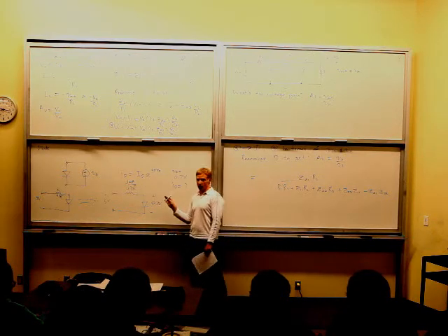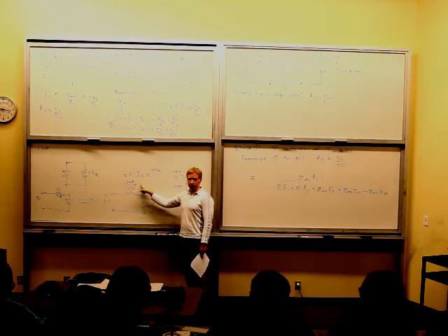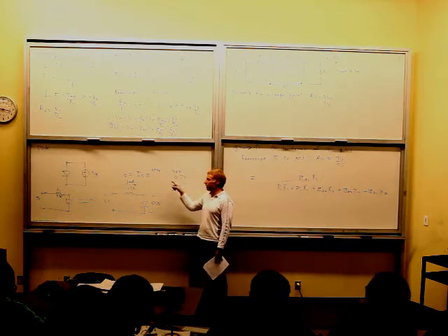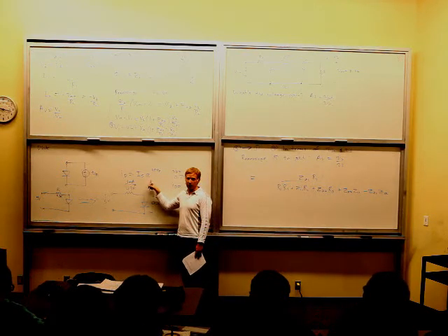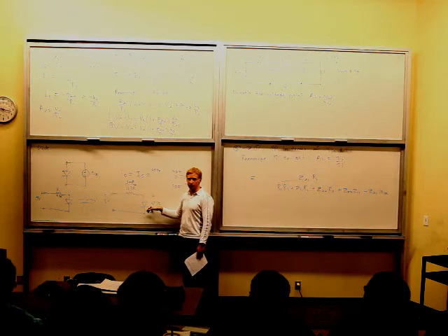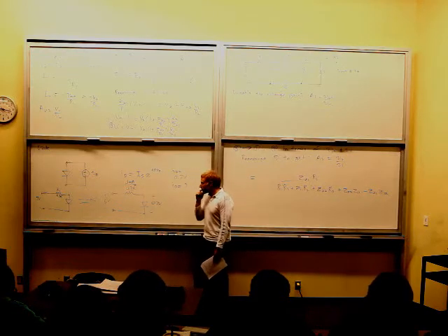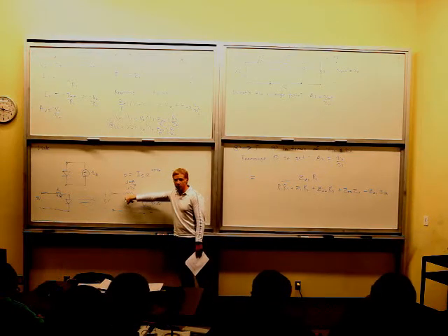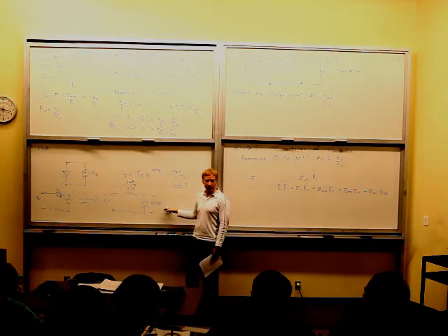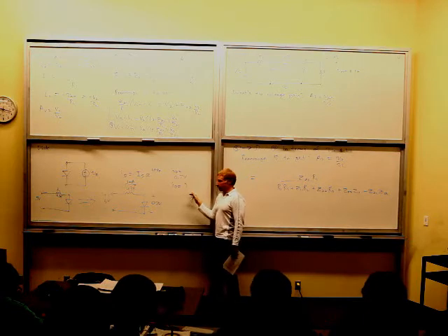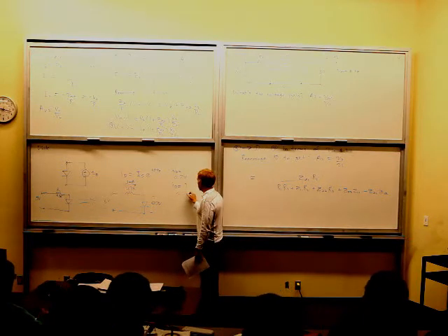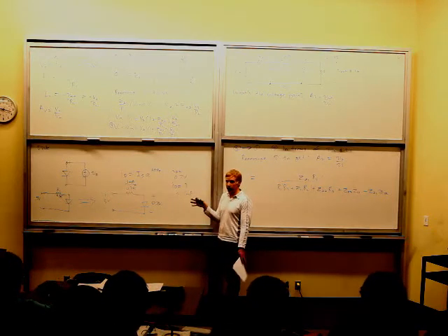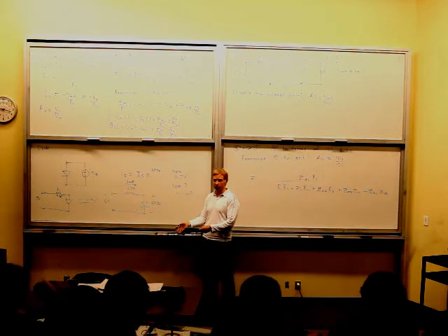If it's way off, if you get 100 amps going through this thing, but they tested it and it was only supposed to be 1 milliamp, now you're going to have to go through that iterative procedure. You're going to have to make a better guess of what that voltage across the diode is. So you have to think intelligently here. Assume that the burden is going to be on that resistor and that you can just put 0.7 volts there. Look at the manufacturer specified value. If it's approximately whatever you came up with, then you're okay. Just proceed on to whatever the second part of the question is.